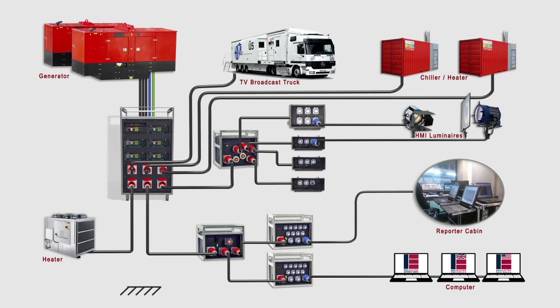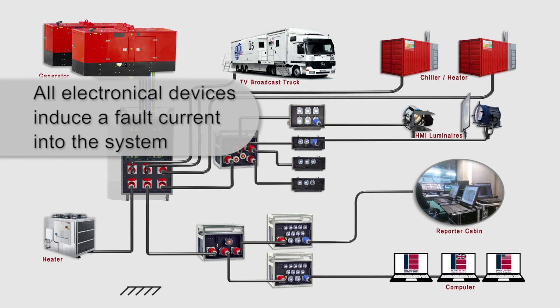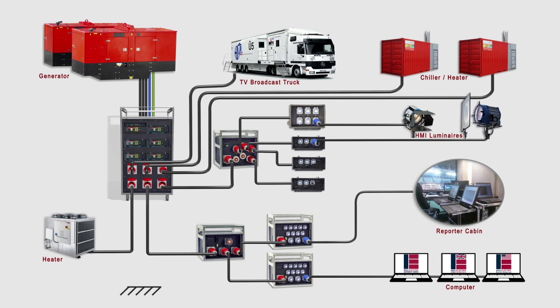Even fault-free electrical devices induce a leakage current in the system into which they are incorporated. There are three types of leakage current: stationary, dynamic, and transient. Stationary leakage current is current that flows to ground or to some other conductive component in a fault-free circuit. This current is generated by capacitors in EMC filters and the capacitance of long shielded cables, and can therefore have a capacitive component.